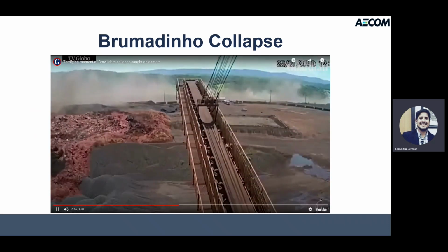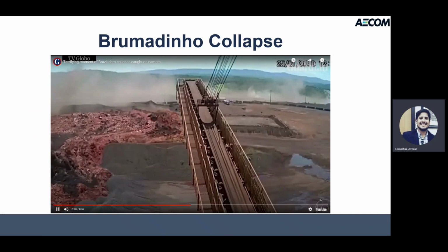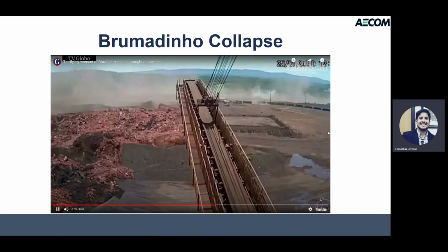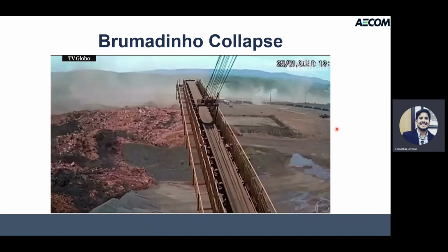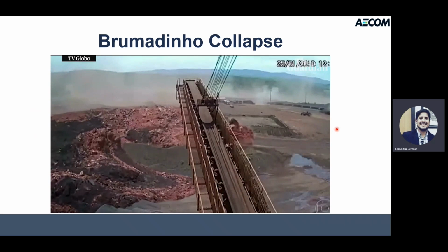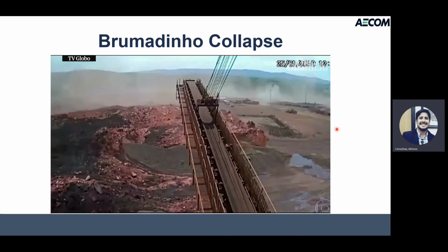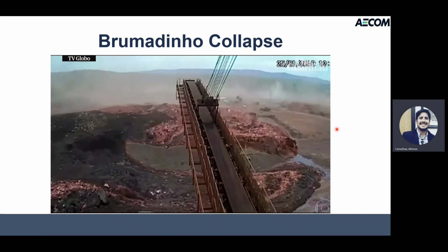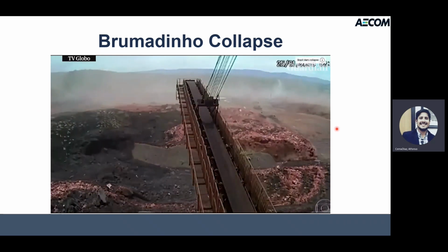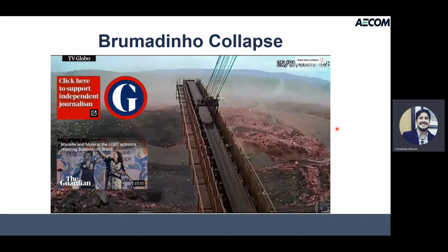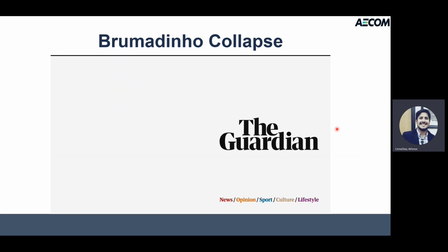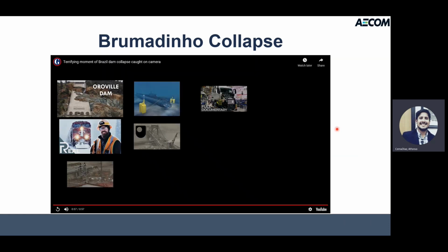There's some discussion of small movement prior to this failure, and some other recent investigations are talking about drilling inducing static liquefaction at specific locations of this case history. However, there's still more work to be done to really understand what happened. Was it merely static, due to loss of bonding over a long time with a subsequent rain event, or was the trigger a drilling process during operation?